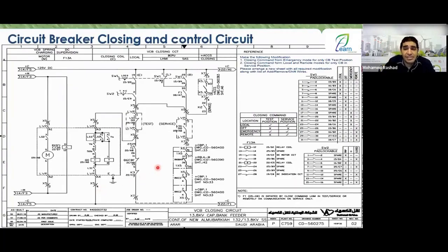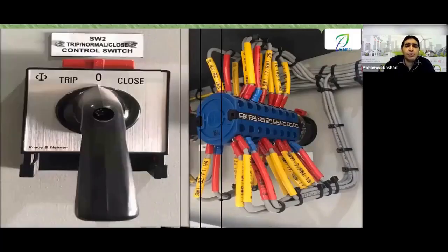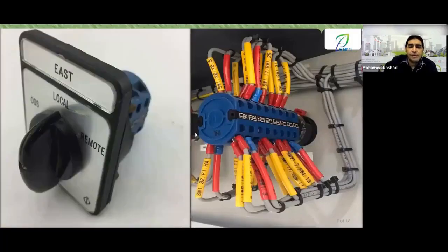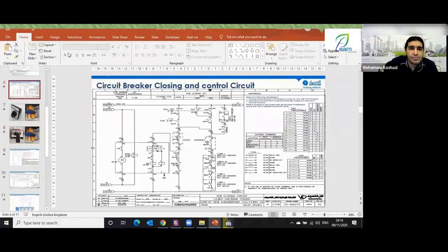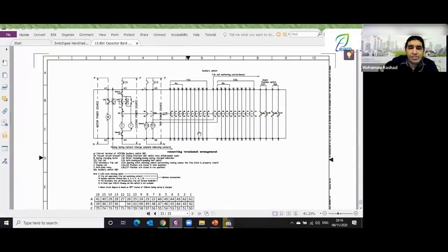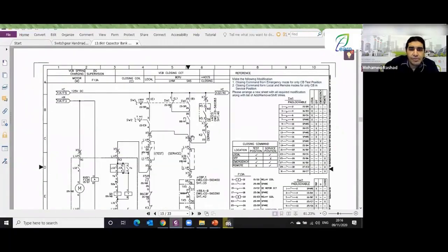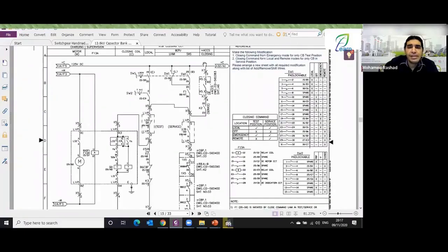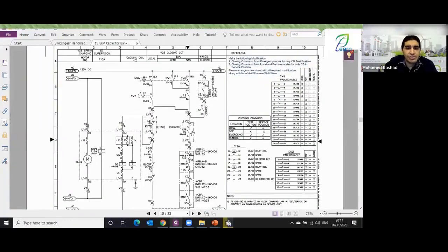Well, look, engineer, this is obviously a mistake by the person who was working with you. Here, in the schematic diagram, it should have been mentioned underneath. If you follow here, engineers, it should tell you the page number, which is, here, like this. I want to come here to my drawing. If I come here like this, engineers, here it is. Here is K2. It was supposed to tell me, engineers, where K2 is coming from.